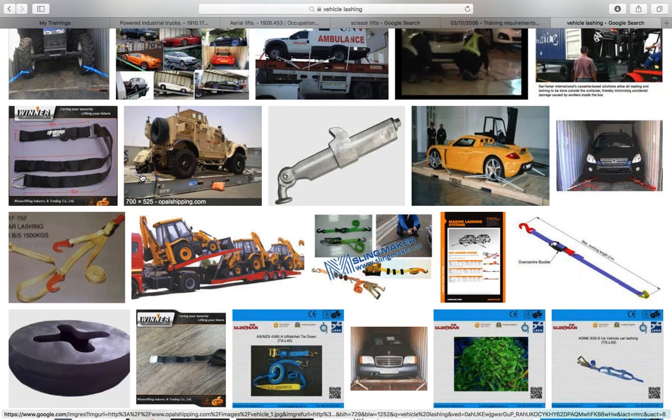Also, making sure that you never position yourself between a moving object and something that's immovable, or even two moving objects for that fact. Also, some heavy equipment is designed to carry heavy loads overhead, right? Never stand under the raised load. Objects could fall, right? The vehicle could suddenly lose hydraulic pressure for some reason. The boom could collapse. So there are all these different reasons why we don't want to be under where the load is. If it's on any type of rigging or slings, wire rope, or a chain, it could fail.